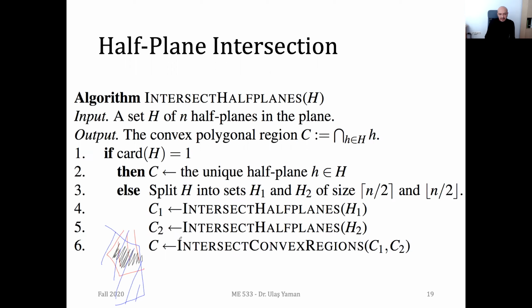So the most complicated part is the last algorithm, the intersection of these two convex regions, how we are going to intersect these two regions together and have a feasible one. So now our problem is simplified to the intersection of two convex regions. Once you have these convex regions and have completed this intersection properly, then that means you are done and you can simply state whether your part is castable or not. Any questions, guys?